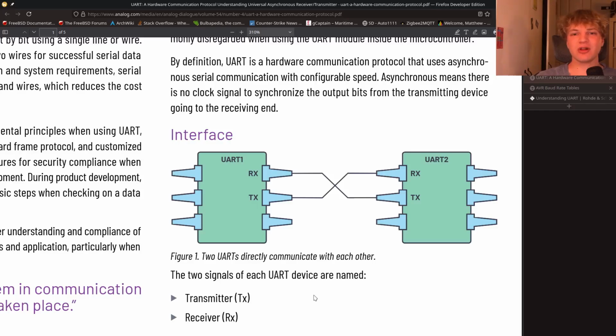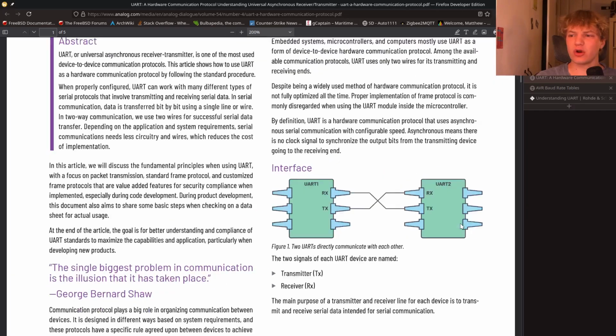So with UART, we typically only really consider two MCUs. Because remember, this other chip can start talking whenever it wants. So there's no master-slave synchronization there. So typically we only use two MCUs. Now, important things to note about UART.